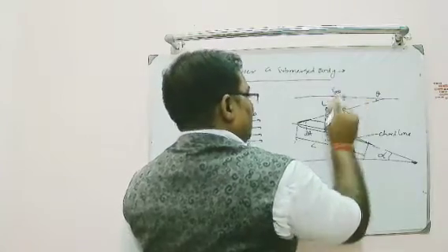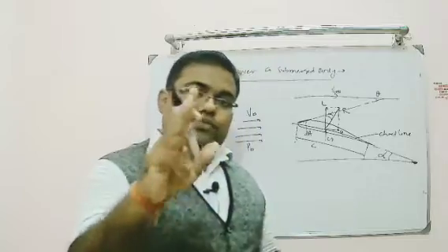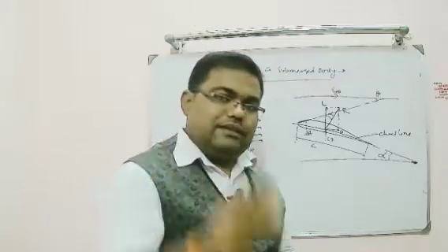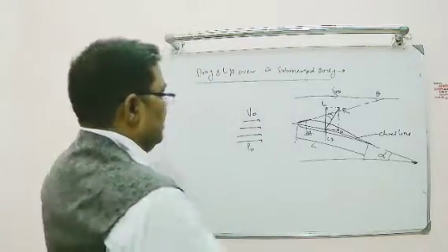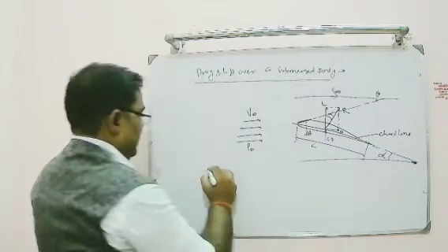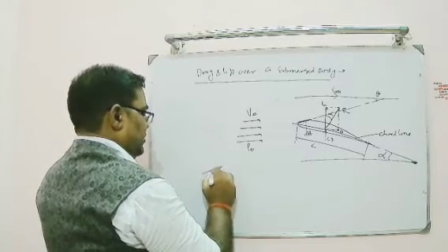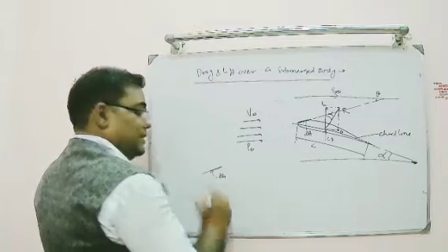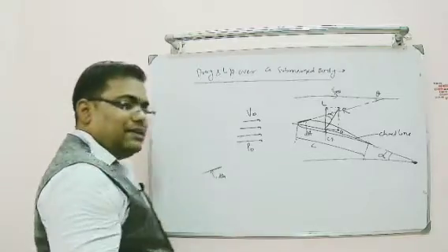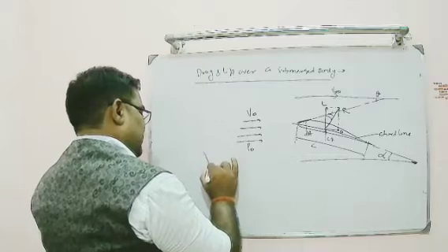So if I want to draw this right here, I will consider only two forces: pressure forces and skin friction or shear forces. If I take this elemental area, this is my elemental area which I consider for my study. This is dA basically. The pressure always acts perpendicular to the area, so this is the pressure which is acting here.